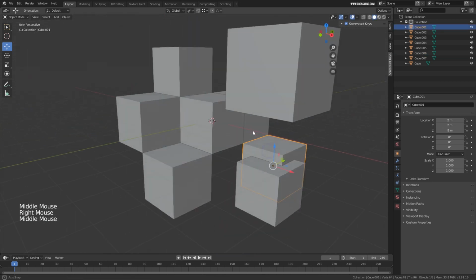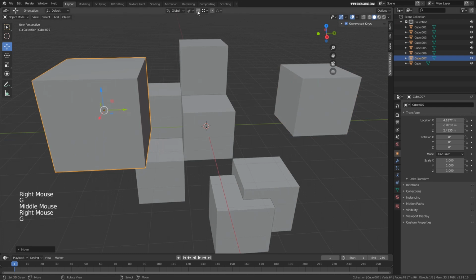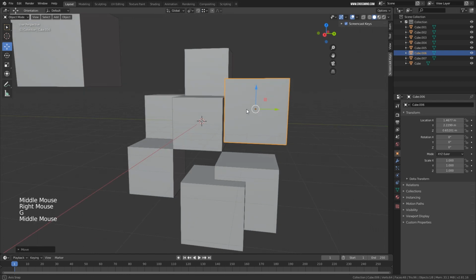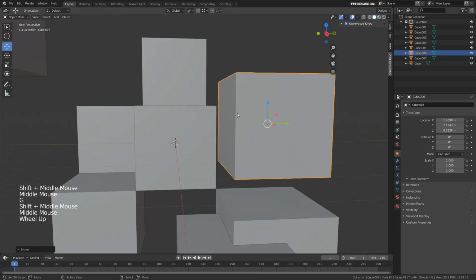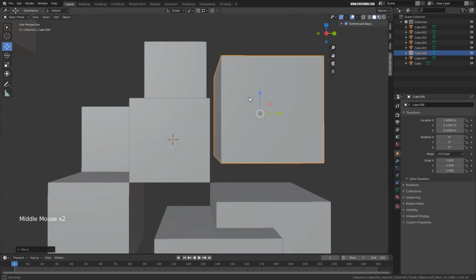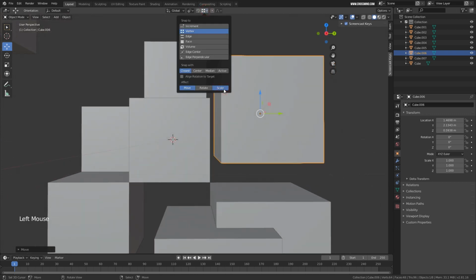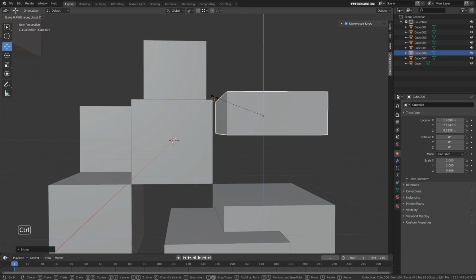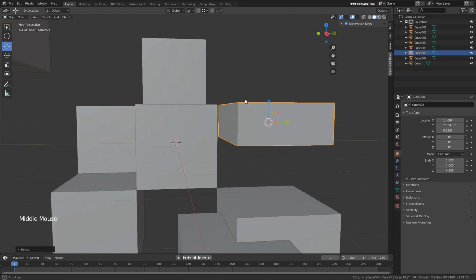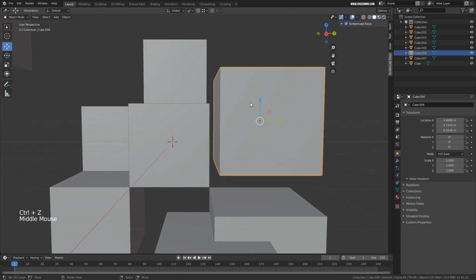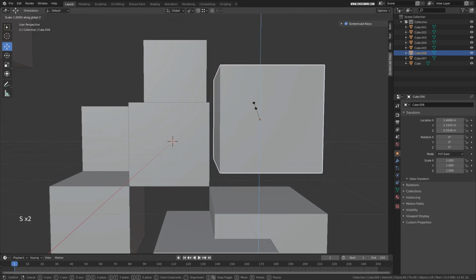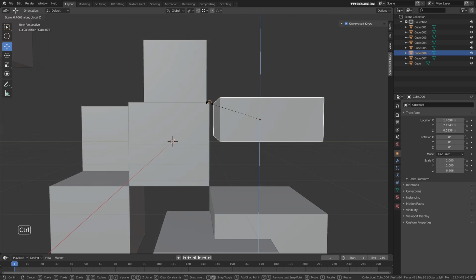Alright, so this is just for the movement, and there are other options. If you want to rotate, scale and use the snapping, that also works. Let's say right now this object, I want to scale this to this height, then I can enable scale as well. Now if I try to scale this one and press Ctrl, then when it reaches this point's height, it will stop. It will snap to this height. So you can use this in scaling as well. Sorry, scale in Z direction, S, Z, and press Ctrl to that point and it will snap.